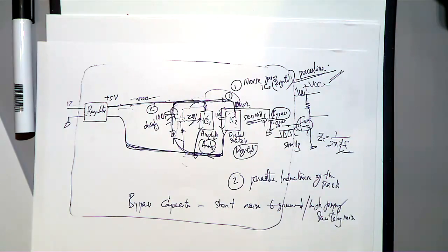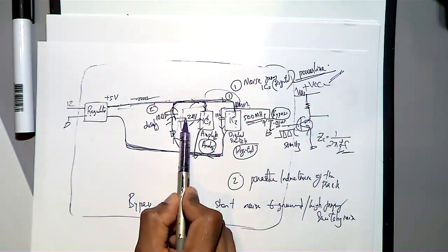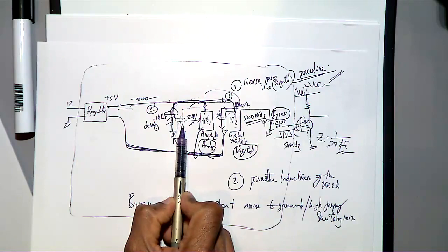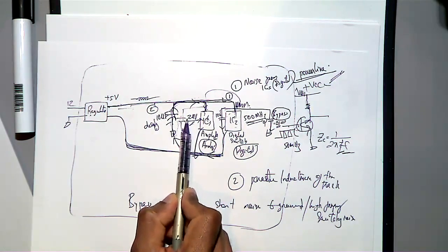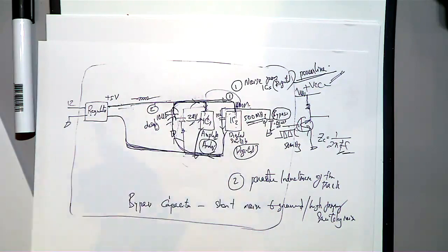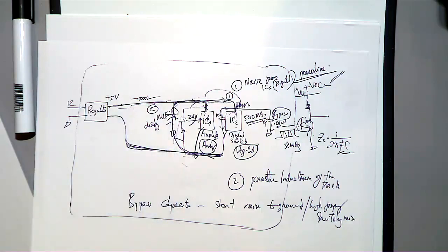No sir, I'm saying why not use a very big capacitor, or only two capacitors, one for decoupling and one for complete bypass? Now, it is very difficult to get one value here, because if you are putting only one, the value should be very high, and in surface mount you don't get that big a value. So you can get maybe 1 microfarad, 0.1 microfarad, or usually we put nanofarad because that's small, and then this should also be tuned to a particular frequency. Yes, if you put a bigger value it is good, but then you should put a very big value, not 0.1 microfarad, maybe 10 microfarad. The advantage of 10 microfarad is that it will also give a power supply. It's an active power supply. It will also short the noises in most of the frequency region, but the problem is that you are increasing the size.